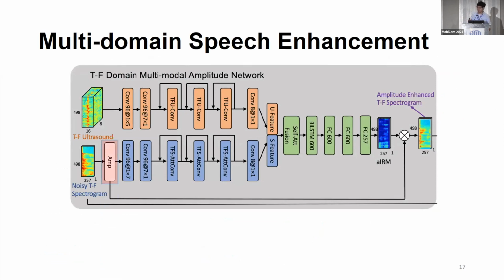Now we only consider the amplitude of the speech spectrogram in our previous design. The reason why we do not consider the phase in the beginning is because in the time frequency spectrogram, most of the phase information is useless and random because their amplitude is really low. However, we find that when the speech signals are significantly noisy, the phase of the spectrogram will be significantly distorted.